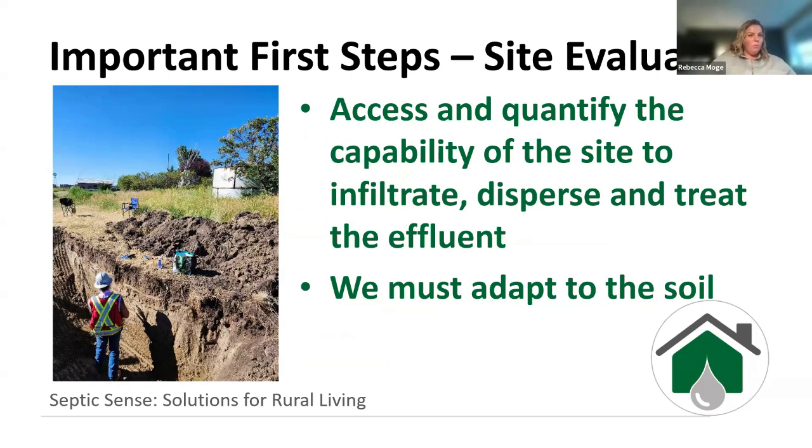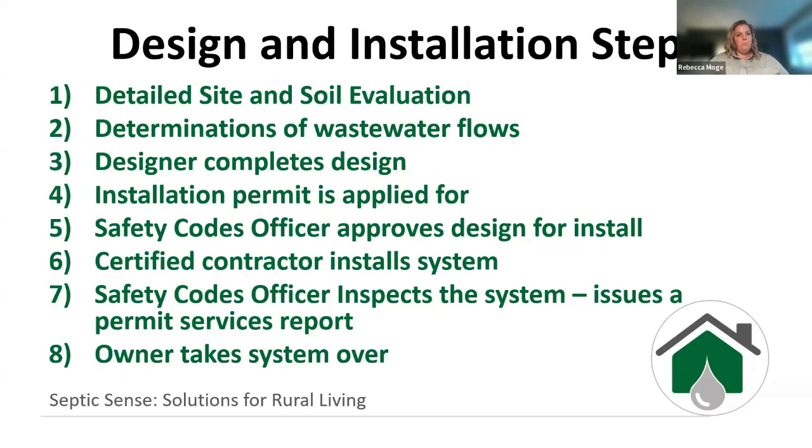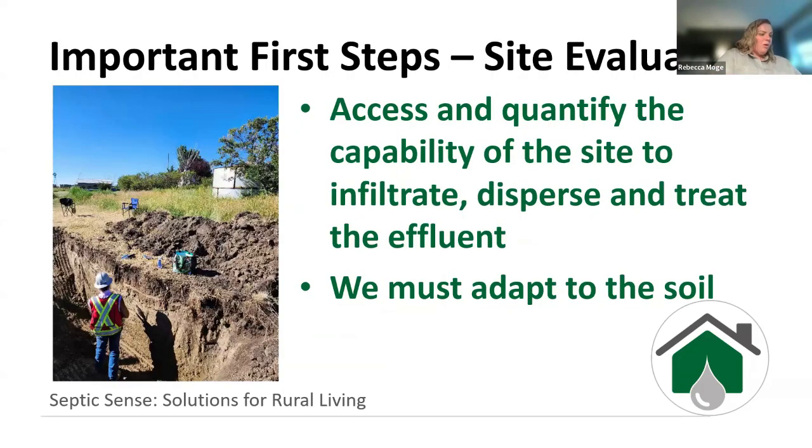So with our site evaluation, we're looking at the capability of the site. So again, we talked about any limiting factors on the property, the water source, even the slope and grade of the property impacts the system or where it can go or where it should go.